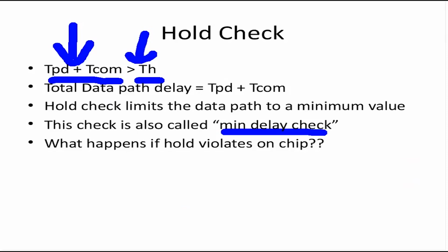That is the idea. But we know that worst case corners, the corners that have more delay on cells, will be more critical for setup. The corners that have less delay on cells will be more critical for hold. Right. So again, the bottom line, max delay and min delay. These are the two things you have to remember. Max delay is setup, min delay is hold.